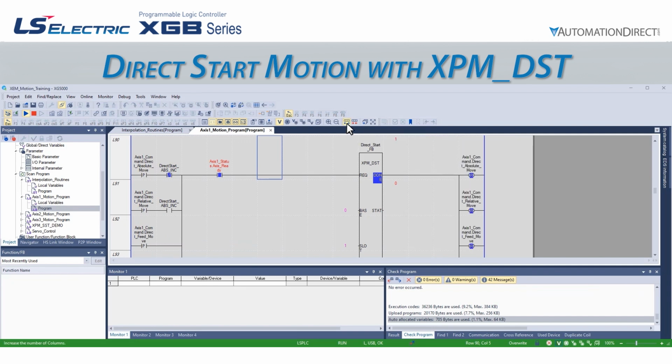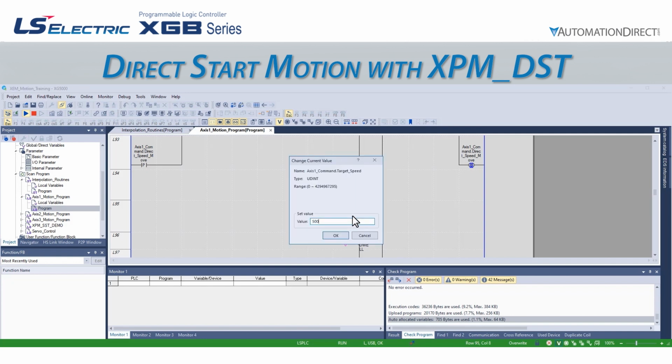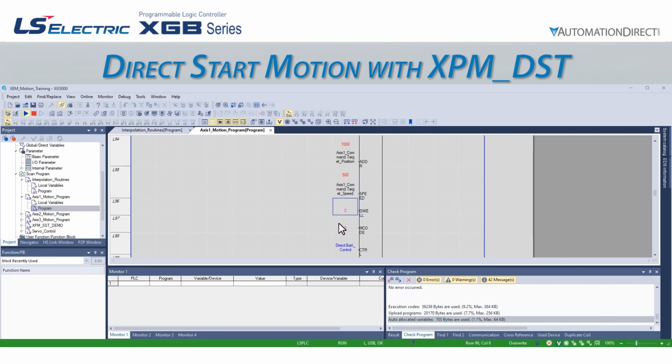Now if we look at line 90, we see that if we are commanding an absolute move, and the program is in absolute mode, and axis 1 is ready, we will request a direct start. This direct start will command base 0, which is our main PLC base, slot 1, which is the onboard pulse motion controller, and axis 1, which is the x-axis in our system. Let's move to a target of 1,000 pulses at a speed of 500 pulses per second. Our dwell time will be 0 when we get to the end of the move, and we aren't using the mcode function for this move. Our control value is currently 0, which corresponds to a position move.